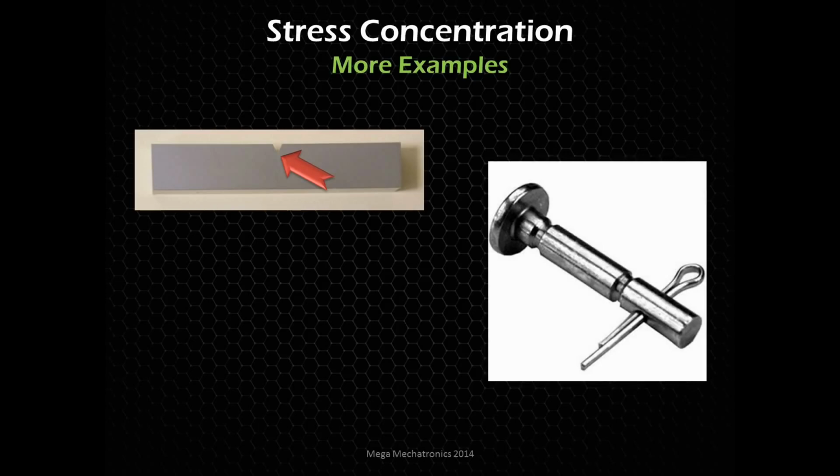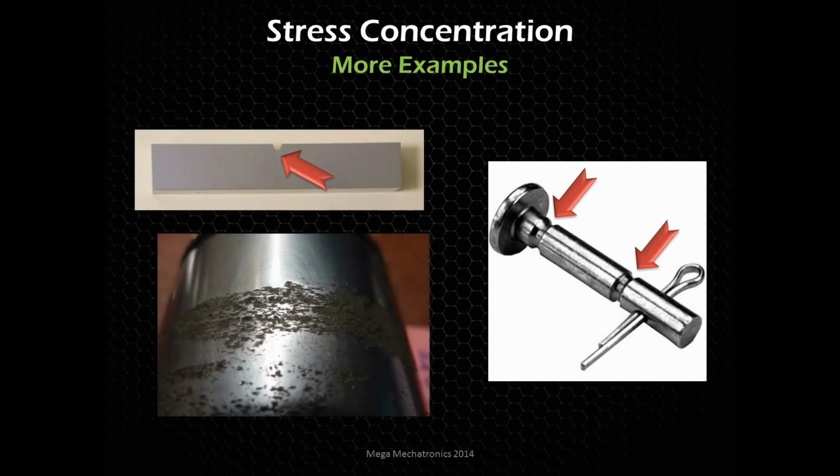And let's look at the shear pin on a snow blower, where you can control how the part fails and the failure mode. If something gets jammed in there at a certain force, this pin will break at these points and give us a predictable and most likely safe way of breaking.